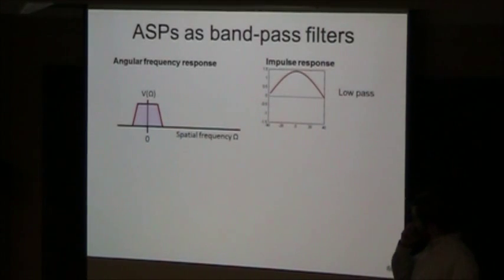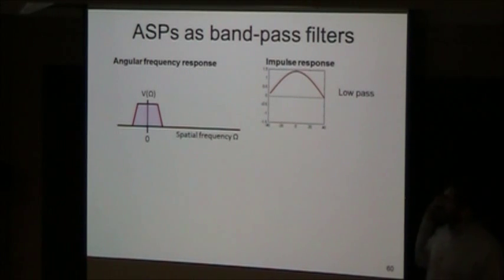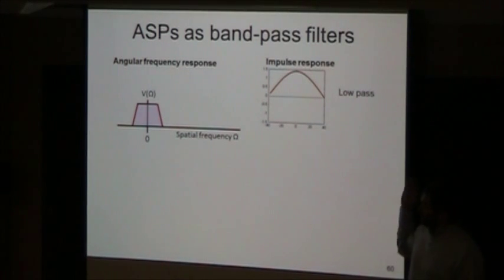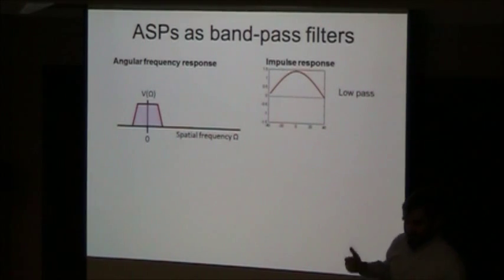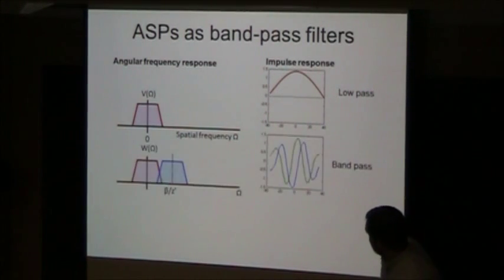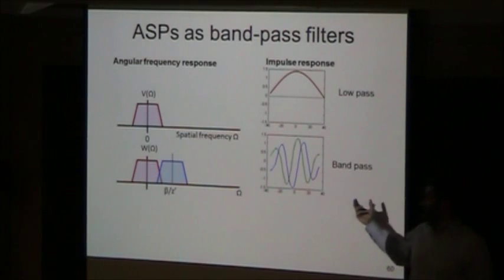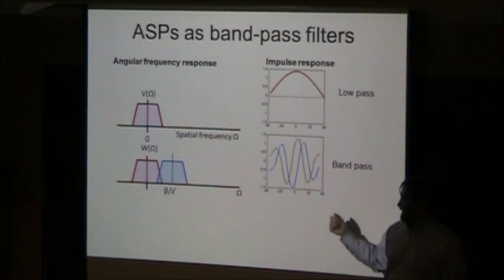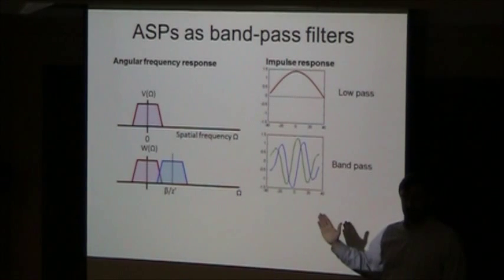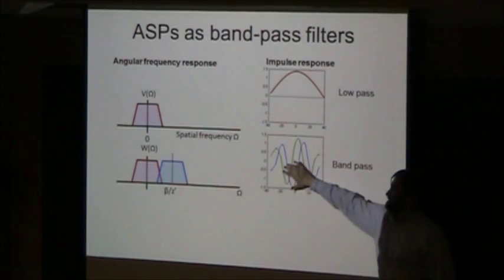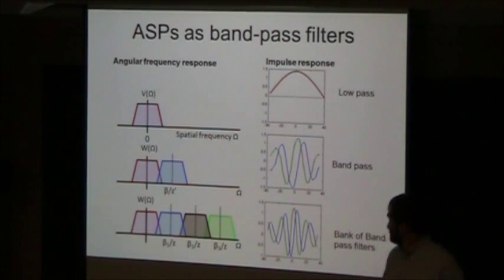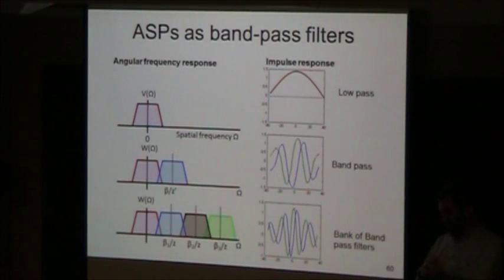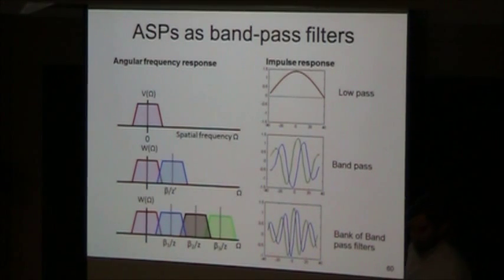One realization from a signal processing perspective is that what we're actually building here are a set of filters. So our raw intensity number is essentially a low-pass filter whose bandwidth is set by how out of focus you are. But our angle-sensitive pixels are actually acting as bandpass filters, responding to particular center frequencies set by the periodicity and bandwidth set by their envelope. And we're generating multiple of these. So we're generating a whole array, essentially, of bandpass filters on our CMOS.